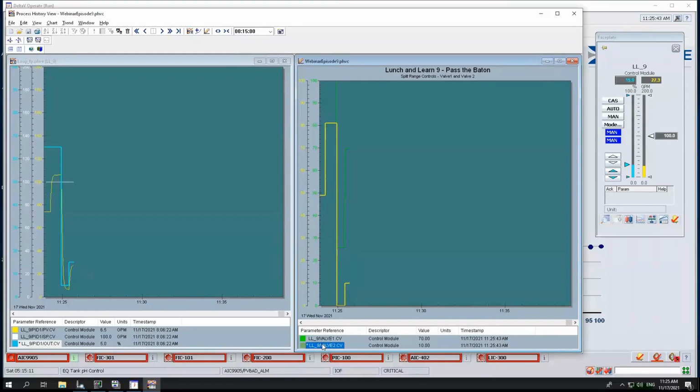So we're now starting to open up both of them, hopefully in a coordinated fashion, to make sure that throughout the range we can have a more constant process response. And that's the idea behind this. So it's not only asymmetrical, you can see here, I'm opening it sooner on the big valve, but at the same time, I'm also overlapping both of them.